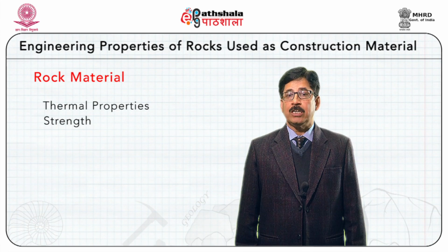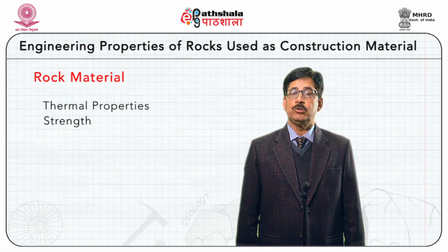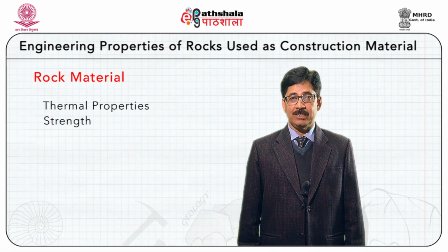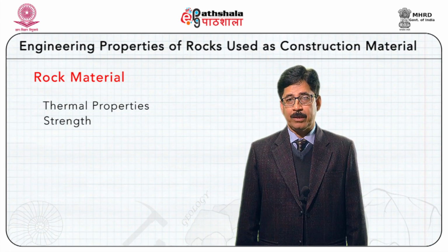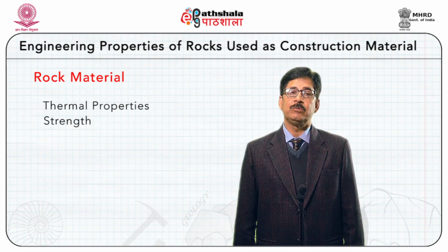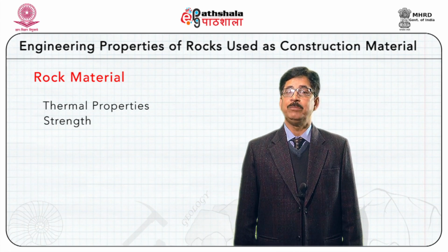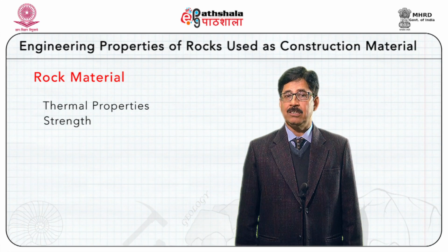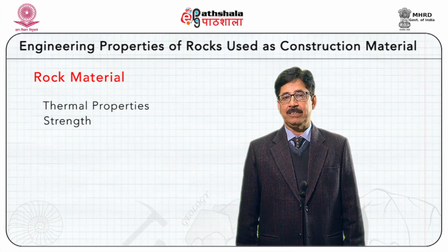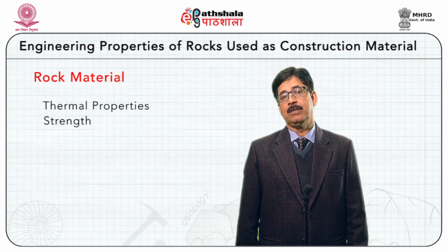Rocks which are below the ground surface are subjected to loading from all the sides. So that's why triaxial strength is also important. For a faster test of strength of the rocks, we can use an instrument which measures the point load strength test, where we can have a small sample and test it in very short time using a point load strength tester.